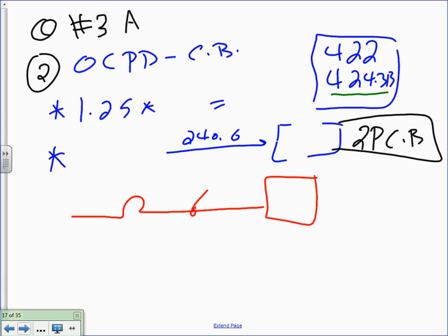It tells you to size it as a continuous load heating element, 1.25. So what was the full load current for that one again? 95. And we did this one, 118.8 amps. So 118.8 amps at 240, what would that give you? 125? I don't think there's a 120. 125 amp. I have a 2-pole circuit breaker, 125 amp.